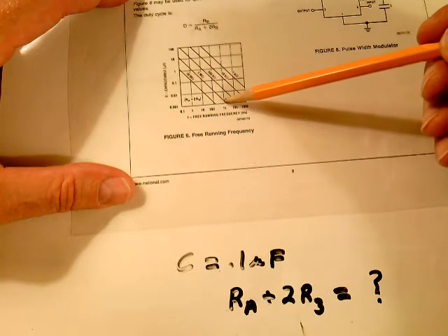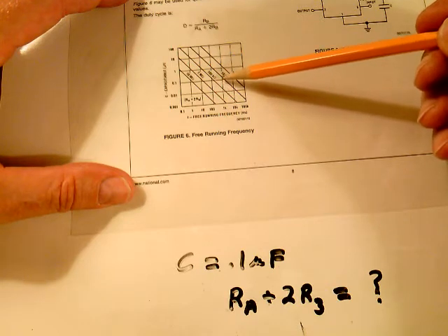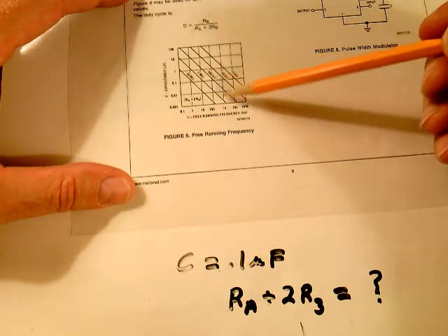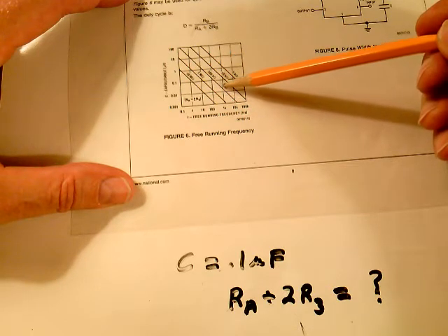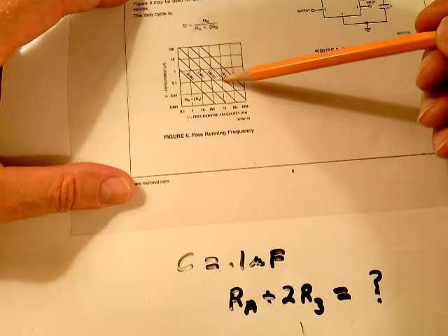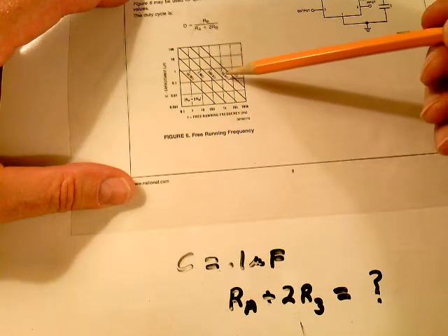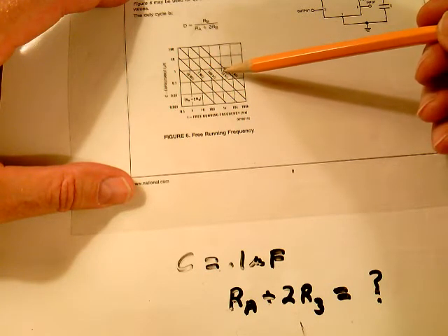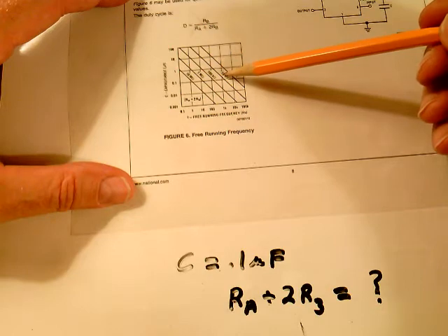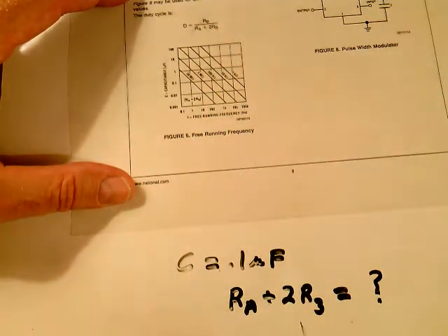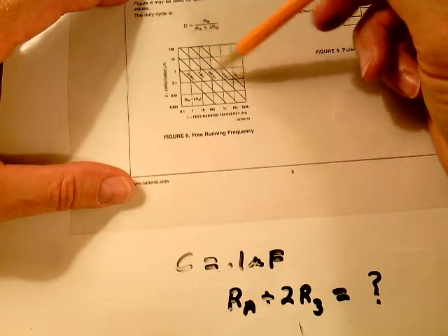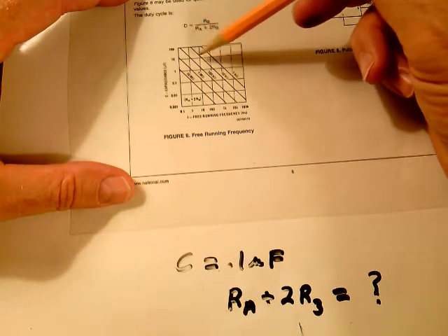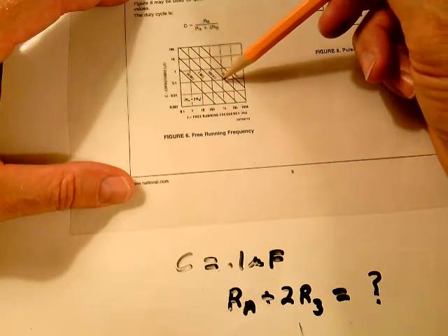It's hard to read this, and you go up, and you see where that vertical 2 kilohertz line would intersect the 0.1 microfarad, and it isn't going to be on the 10 kilohertz or the 10 k ohm parallel line there. It's definitely not going to be on that line. So you're going to have to interpolate some parallel lines and have another parallel line coming down through there.